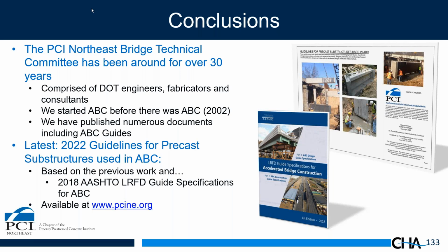And it really is a connection. You're connecting a footing to the subgrade. That is a connection. And the flowable fill, this is in the guide spec, but the key thing is, as I mentioned, the pressures that are underneath footings are in the magnitude of 100 to 200 PSI, not KSI, PSI. So you don't need a 5,000 PSI grout. You can use non-shrink grout. It costs $6,000 to $7,000 a yard, but you can use flowable fill that costs a fraction of that number. And it's very flowable and it's perfectly adequate structurally to take the loads that we typically see under footings. Okay, that was some of the difficulties.